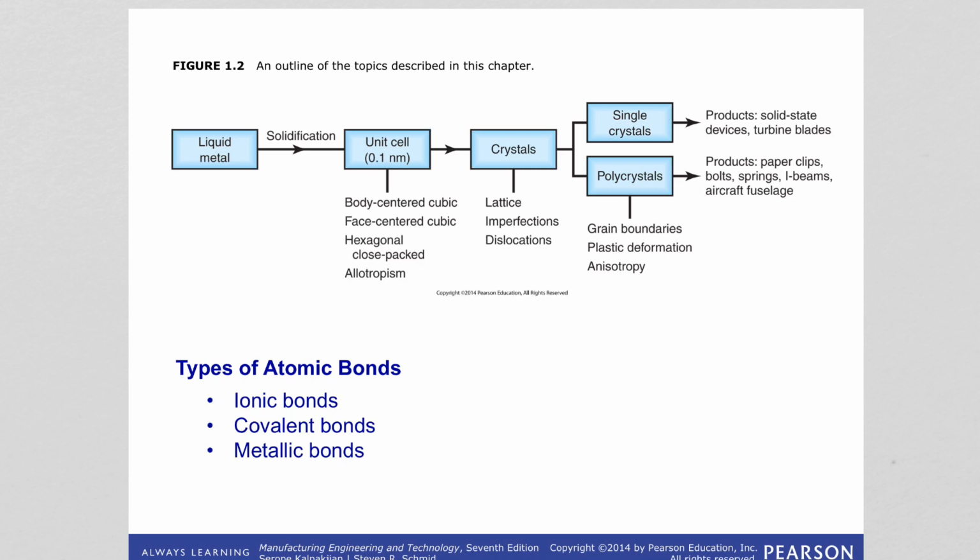And the unit cell is what we learned as BCC, FCC, HCP structures. And determination of properties starts from the formation of unit cells. Okay, so BCC metals will behave differently than FCC. This is how important the atomic structure, atomic configuration is.